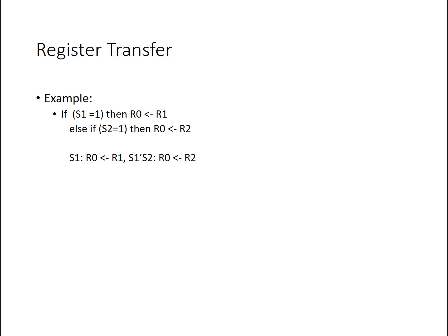As we scale up the systems that we'd like to build, and their complexity and the amount of logic they require, it's useful to have a slightly higher abstraction to describe these digital circuits. And this is where RTL, or the register transfer level, sometimes called the register transfer language, comes in. It's a way that we can express our digital circuits, specifically synchronous sequential circuits, and how data flows through the circuit and is transferred between registers.